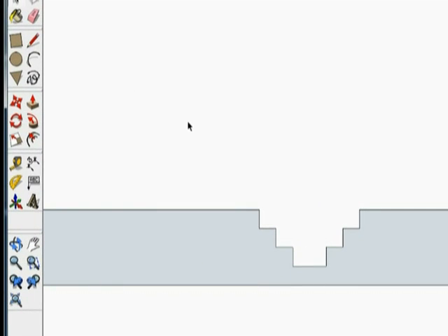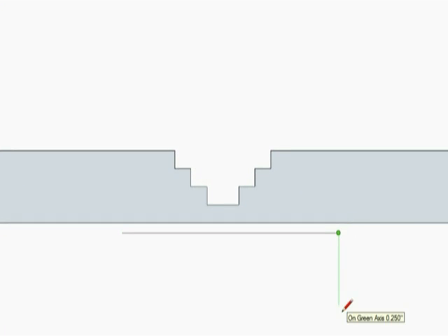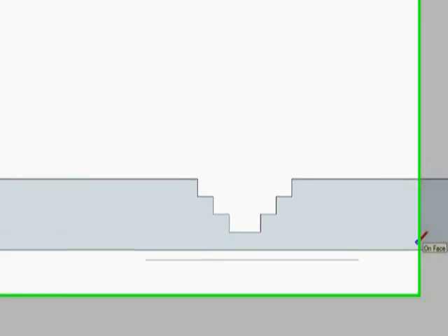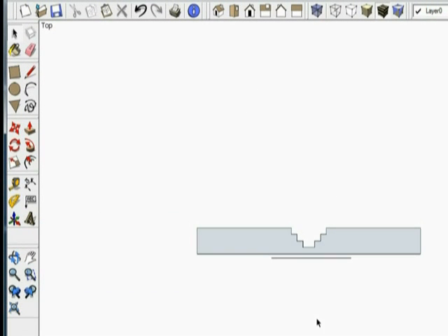And then if you were to put a piece of tape right here onto that foam, and then grab this elevator and flex it up and down, you're going to have a nice live hinge there. So that's a neat tool that you can use for making hinges with your CNC machine. It's a very useful tool, and a very clever use of that tool.